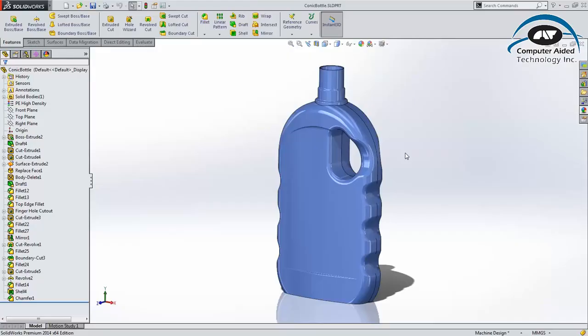In consumer product design and other applications where aesthetics are important, constant and variable radius fillets have limited use due to the sharp change in curvature. Curvature continuous fillets produce smooth results but are limited to a single constant radius. Now the fillet feature in SolidWorks 2014 gives you even more control to define a new type of shape, a constant or variable radius conic fillet.